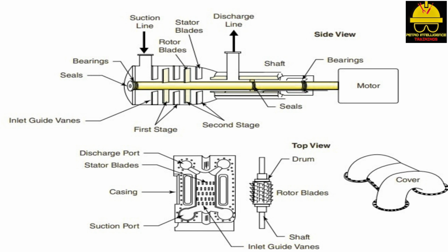The stator blades in an axial compressor can be fixed, individually adjustable, or continually variable. Individually adjustable stator blades can be adjusted from outside the casing. Continually variable blades are adjusted by a drive ring linked to a driveshaft that is automatically actuated by a power cylinder. In contrast to a centrifugal compressor, axial compressors accelerate and compress gas in a horizontal, straight-through motion, without the turbulent changes in direction characterized by centrifugal compressors.